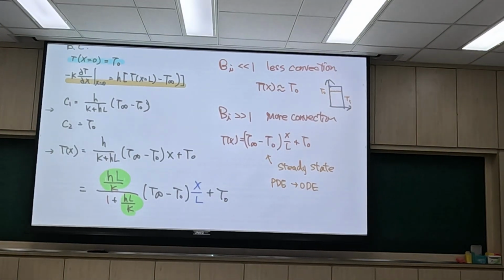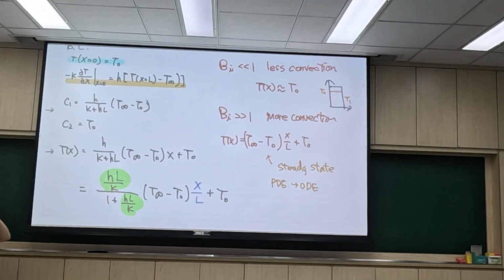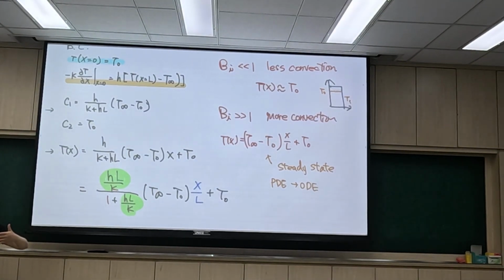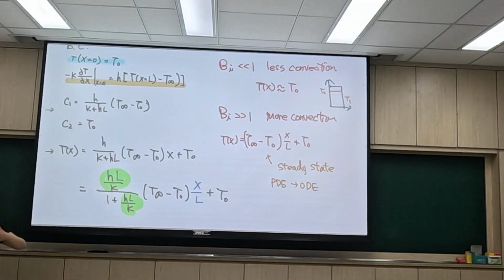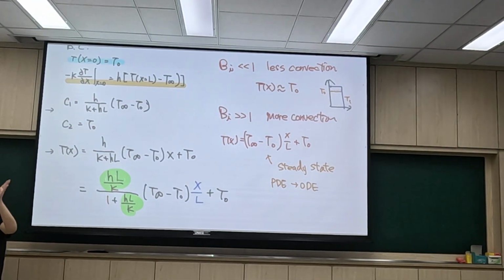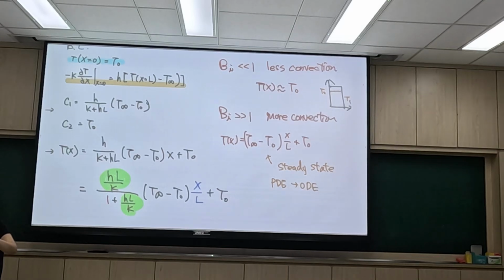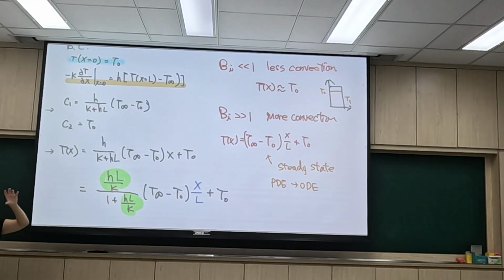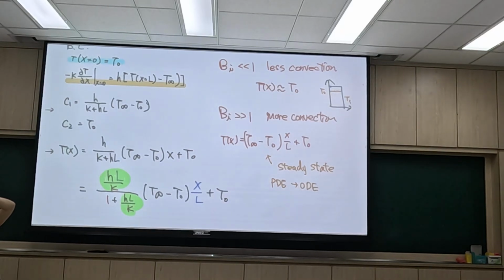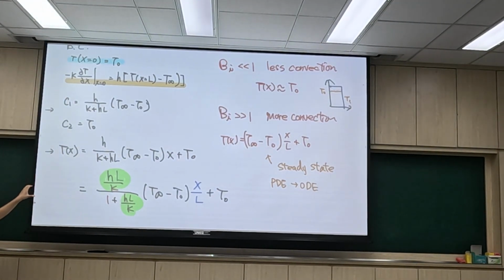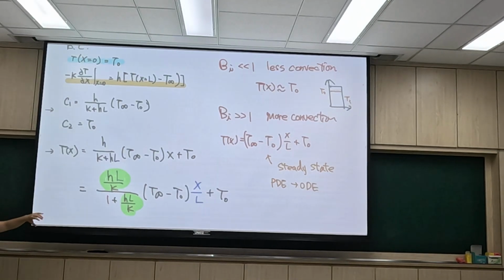The physical meaning is that the Biot number is really huge, which means the heat comes into the wall and is immediately brought out on the other side. So there's a steady state, no nonlinear behavior inside, so the temperature profile becomes linear.